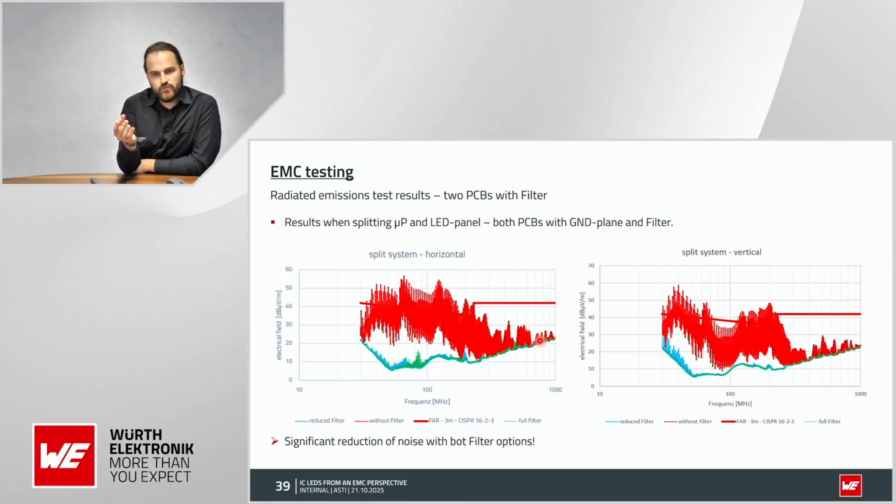From an emission point of view, we can show more or less, when we think of the AC to DC power supply, that with the split system we can pass the test when we use a shielded cable or when we use the filter components.